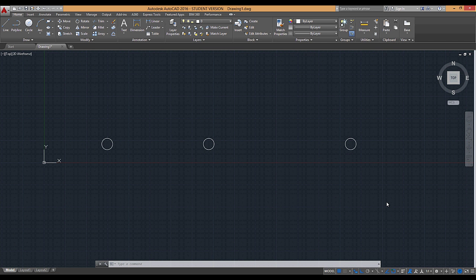To introduce the O-snap button, the O-snap function allows you to precisely connect objects to various points on other objects: corners, midpoints, intersections, etc.